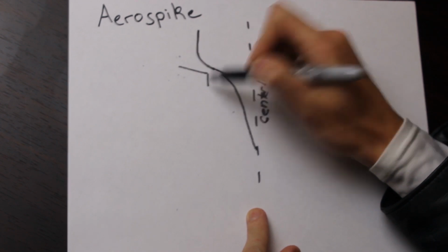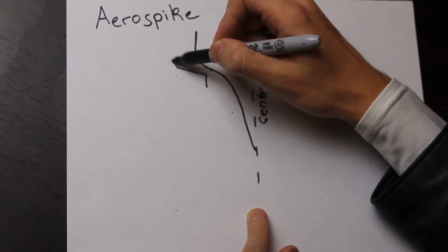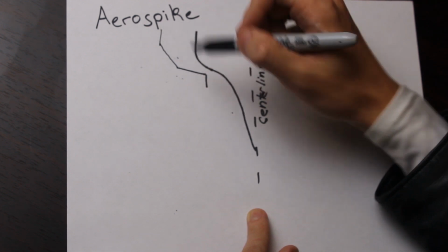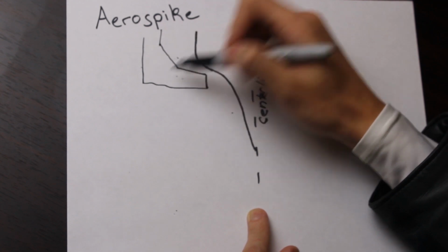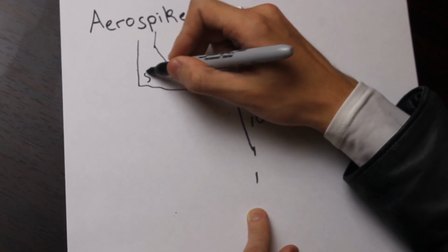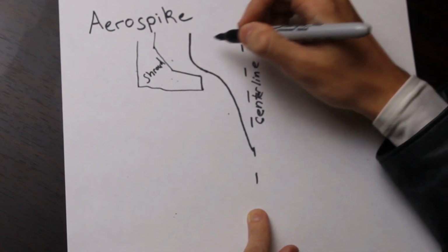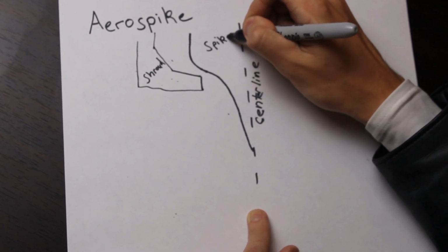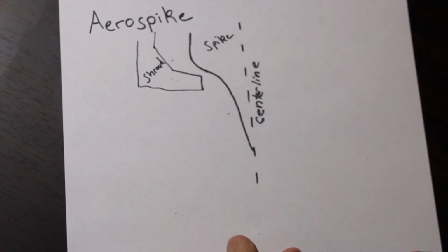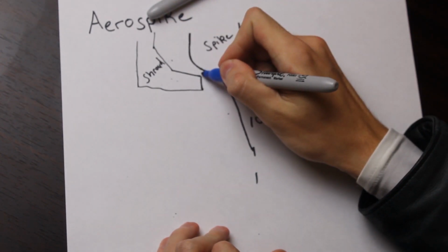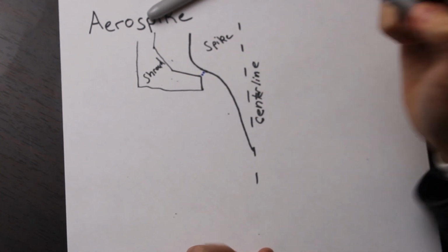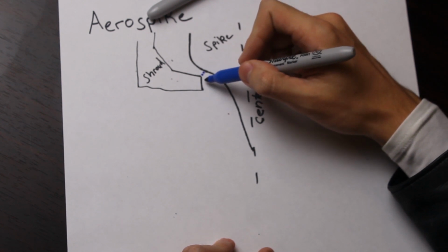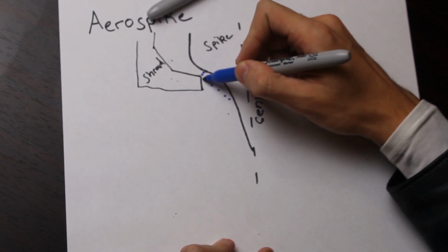Quick here, draw the spike and the shroud geometry. So the spike is this thing here in the middle, and this shroud is this assembly off to the side that forms the lip of the chamber. So shroud, and then this is the spike. So then this in here is the combustion chamber, and then this right here is going to be our throat plane. So the throat plane is the smallest constriction, so that's where the gas is going to go supersonic. And then as we were discussing earlier, we will have our expansion fan.